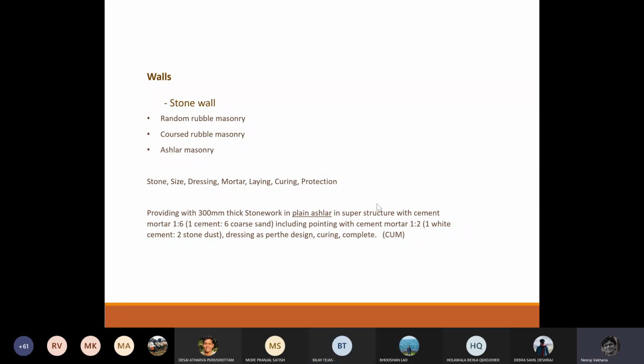That's why for every particular thing, plaster we are keeping separate, because that is another item which may or may not be applied to all the walls. So plaster, paint, tile, cladding, dado, all those things we keep aside and calculate separately. But here cement mortar we have to give for every item because it is a part of that wall.